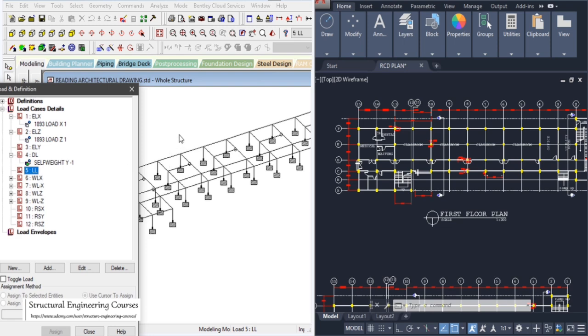See, dead loads are nothing but just simple math: we need to calculate the density of material, then multiply that by the thickness, and then we can apply the equivalent UDL on that. Live load is something that is guided by the codes. For example, if you are referring to the loading for the American standard, you need to refer to ASCE 07. If you are referring to the Indian standard, then you need to refer to IS 875 part number 2 for the live loads and part 1 for the dead load calculations.